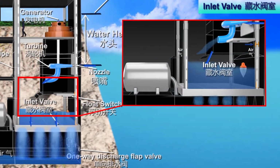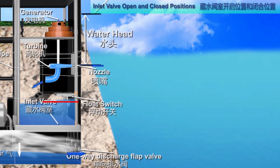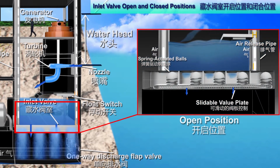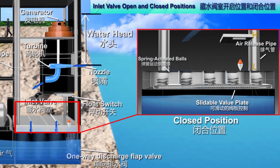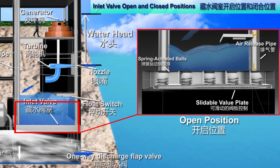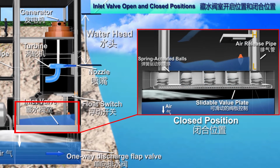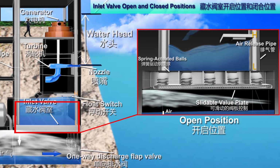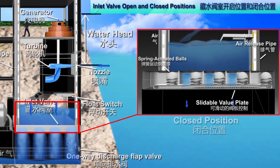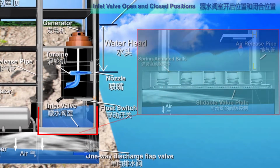The water downstream of the turbine flows into a water-holding intake valve chamber, and the releasing of water is controlled by spring-actuated balls and a slidable valve plate. The regulated intake valve chamber has one or more air release ports to reduce impeded flow of water into the air chamber. When the valve plate is in a closed position, all the holes of the intake ports are sealed and occupied by the spring-actuated balls.